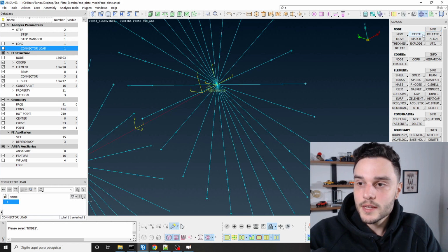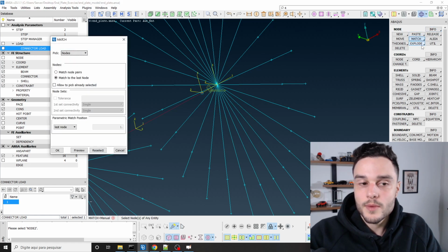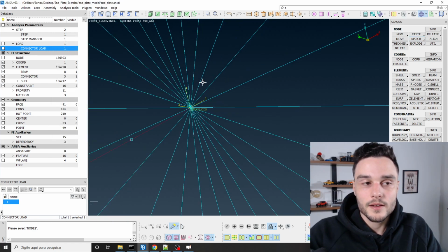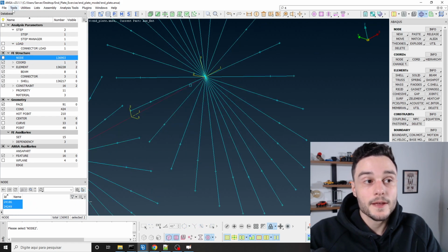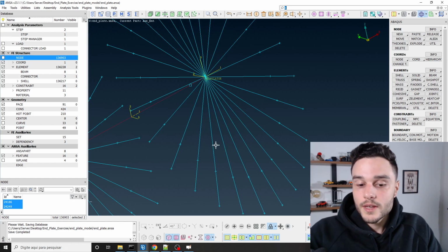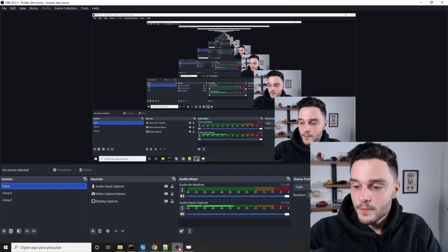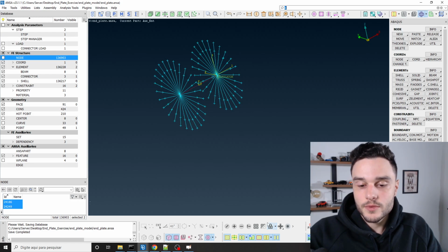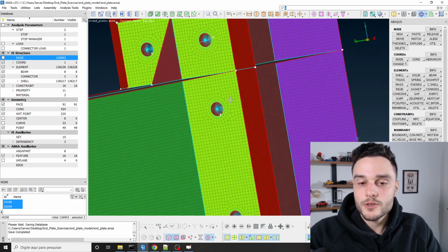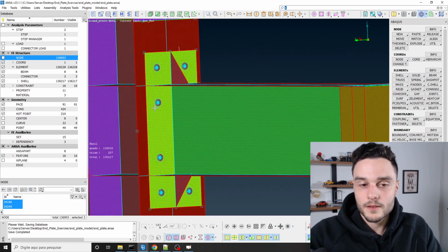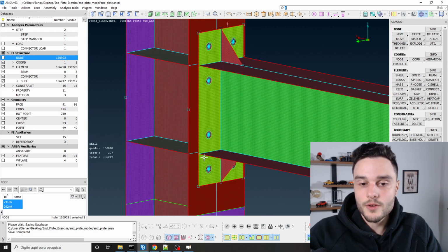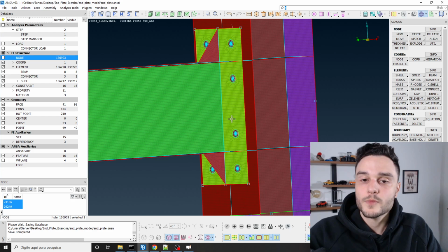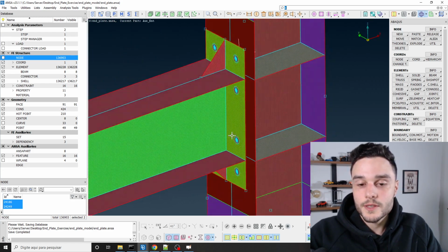Now the last step is to use the match tool, manual. Select this option, last node, from this to this, middle mouse button. Now we have the 2 nodes in the same position. Save this model. And this video is pretty long, more than 1 hour. Unlock this view, click and show all, and now you should continue creating this translator connector for the other bolts that we have here. And then we are going to be finished with this part.